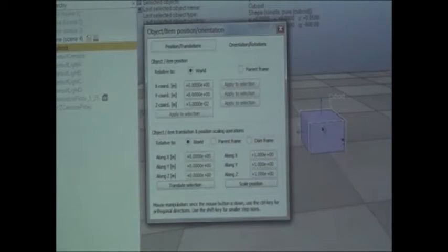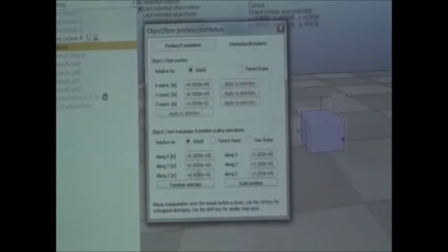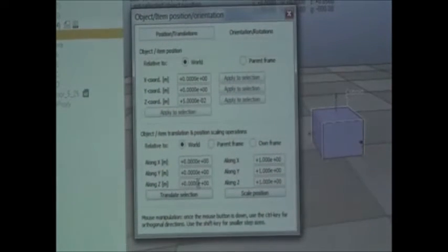Like when you use CAD modeling software, you know that it's better to write the position, the coordinates of your things in the software. In this section it's called relative, but it's the absolute position, related to the initial frame, the 0, 0, 0 of the world, which is right here actually. So either you put the absolute rotation or the absolute position here, or you make some translation. This is translation considering the world frame. This is the world frame, okay?